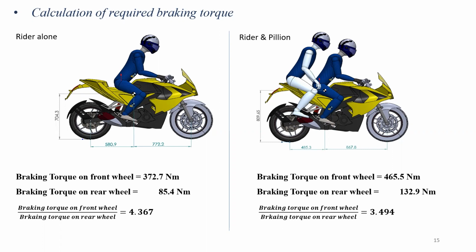For example, if we have a disc which is rotating, and if we have another stator which is stationary, and in between, if I put the fluid, and if I magnetize that fluid, then it will act as a solid part, and a brake is applied. If I remove the magnetic field or the current, it becomes the fluid and the brake is released. So it is a very simple technology. MR fluid is a simple technology. If we apply the brake, it is like this. It is a basic principle only.